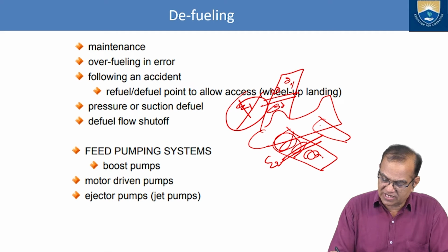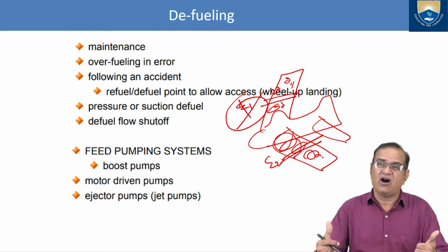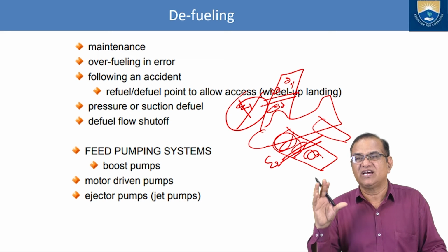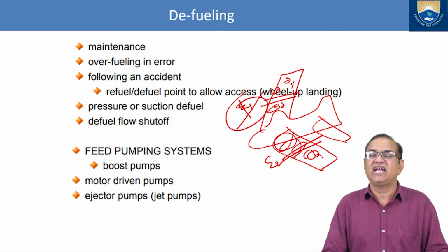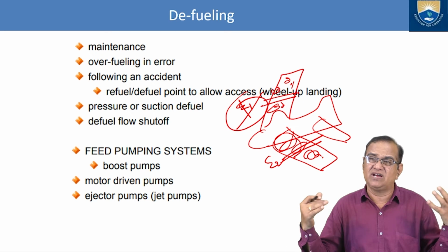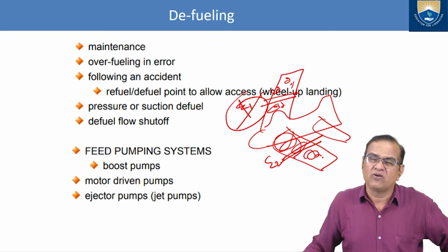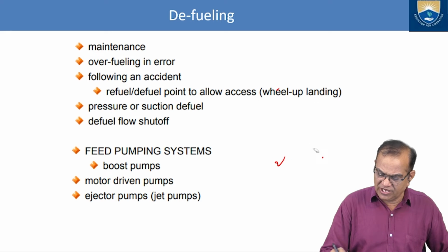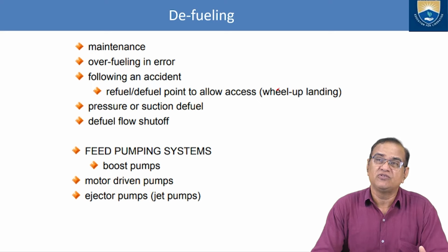So there is defueling, or whenever we want to do some maintenance work on the ground, on jacking up, especially for the rigging of the control or pressurizing or charging the landing gears, or some maintenance in the landing gear, that time we have to lift by the help of jacks. So if your aircraft is filled with fuel, it is very dangerous. So we should defuel the aircraft in these types of conditions. Okay, so the first thing is the maintenance, and I have just told you what maintenance requires us to defuel the aircraft.